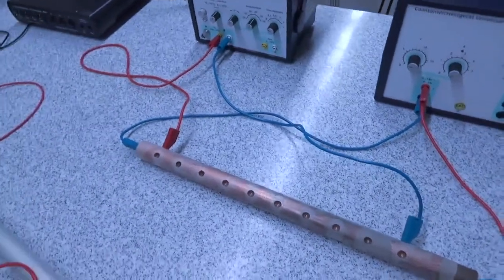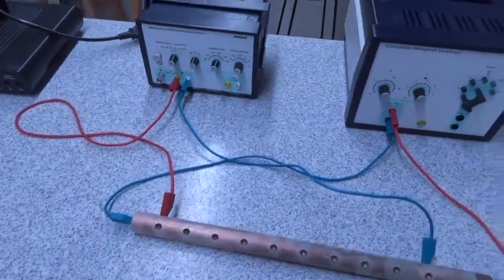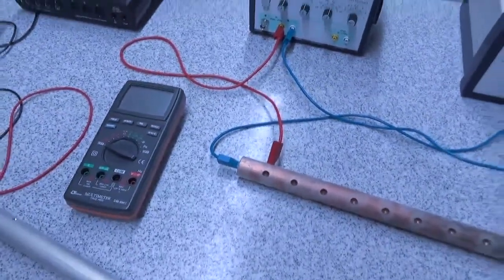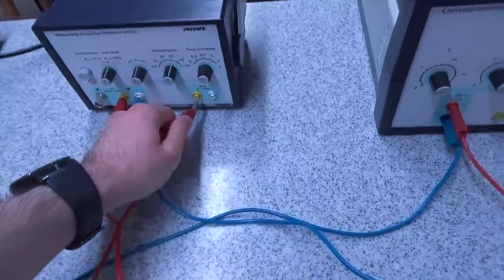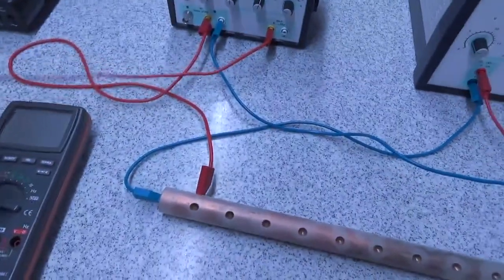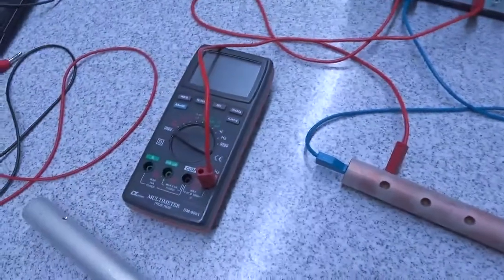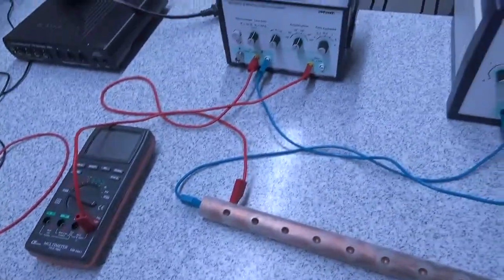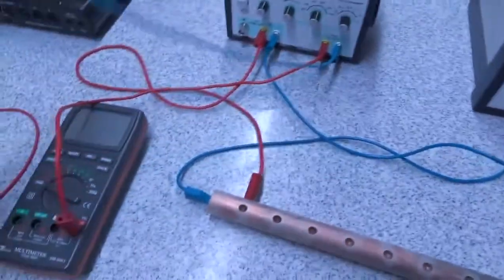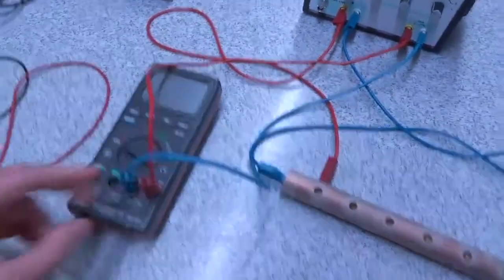Now what's left is to find a value for that amplified voltage. To find the value for that amplified voltage, we are going to bring a voltmeter. We are going to connect that plug over here to the voltage port on that multimeter, and then another connection from the ground terminal, we connect over here across the COM port on that multimeter.